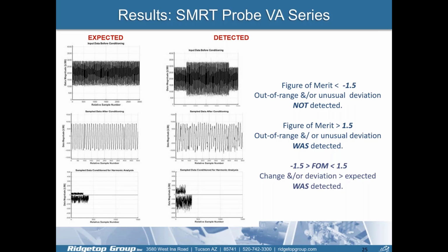And Robert, may I interject something right here? Sure, sure. Yeah. What we do is we expect, as you can see on the upper left-hand corner, and we know that when, and because we observed it, when the power supply is right on the verge of going into the positive range on a phase margin because of loss of gain and Miller capacitance, it begins to break up into oscillations. So you get something that looks like the output on the upper right-hand side.